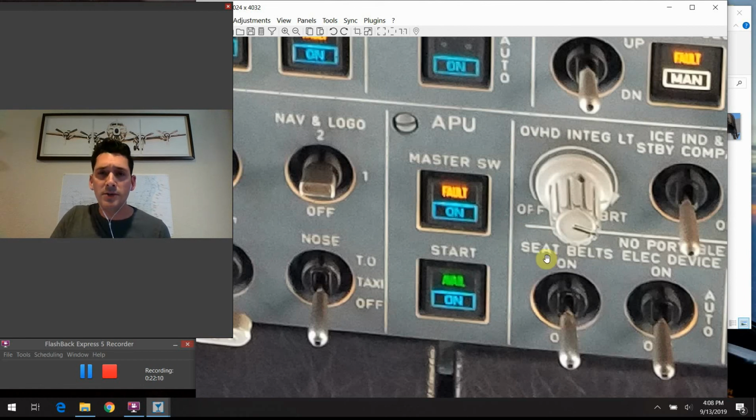Well, if you actually want to start it, you've got to come down to the next button and just very simply use the start button. You press the button once and it spring-loads back out. When the APU has come up to full power and the plane is registering that it's making acceptable power, the green avail light will come on up on the overhead here. And like we saw a minute ago, we had the indication on the status display that would tell you that as well. And interestingly enough, there's a little ECAM memo that will come up on the top engine and warning display there. I forgot to take a picture of that one, but it's pretty simple and straightforward. That will come on when the APU is available.